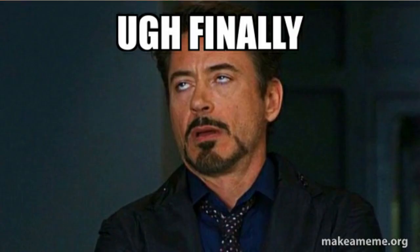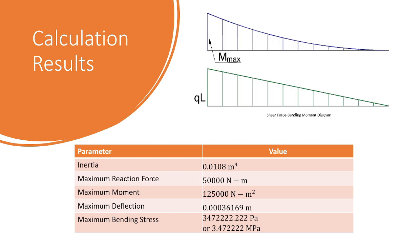Now that we have completed the hand-based calculations, let's take a look at the results. The calculated values for inertia, maximum reaction force, maximum moment, maximum deflection and maximum bending stress are displayed on the screen. The shear force diagram provides us with a visual representation of the beam's response to the load.